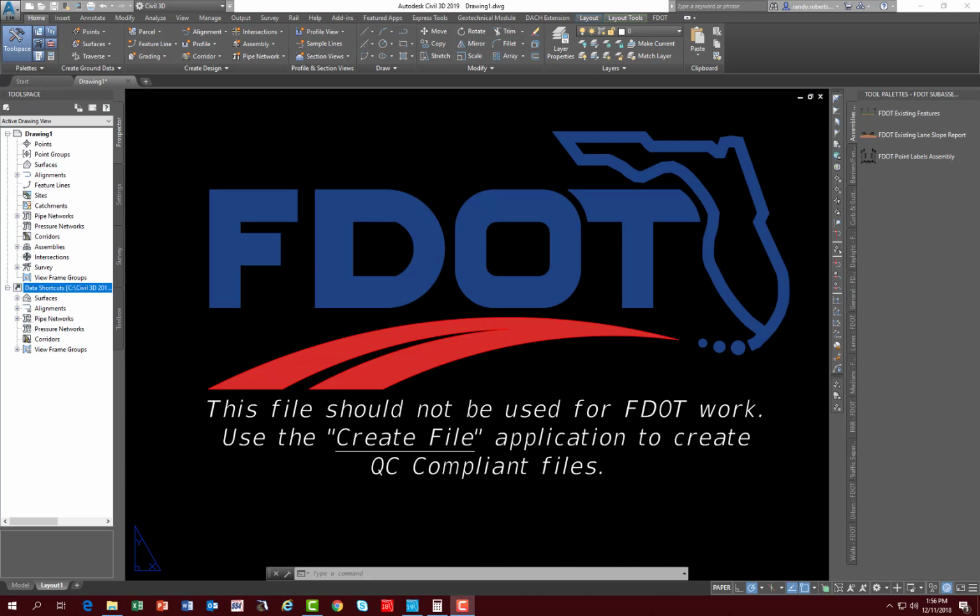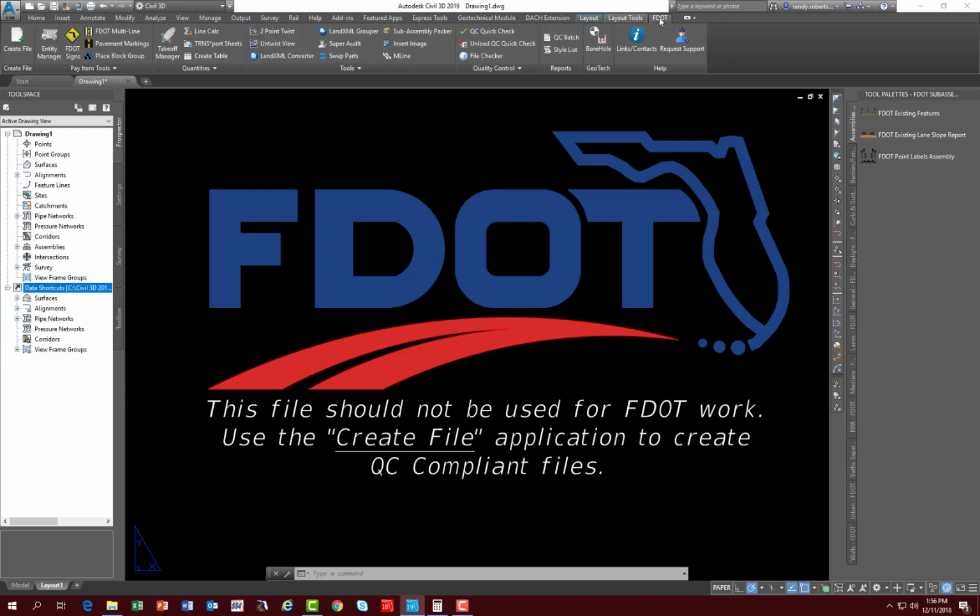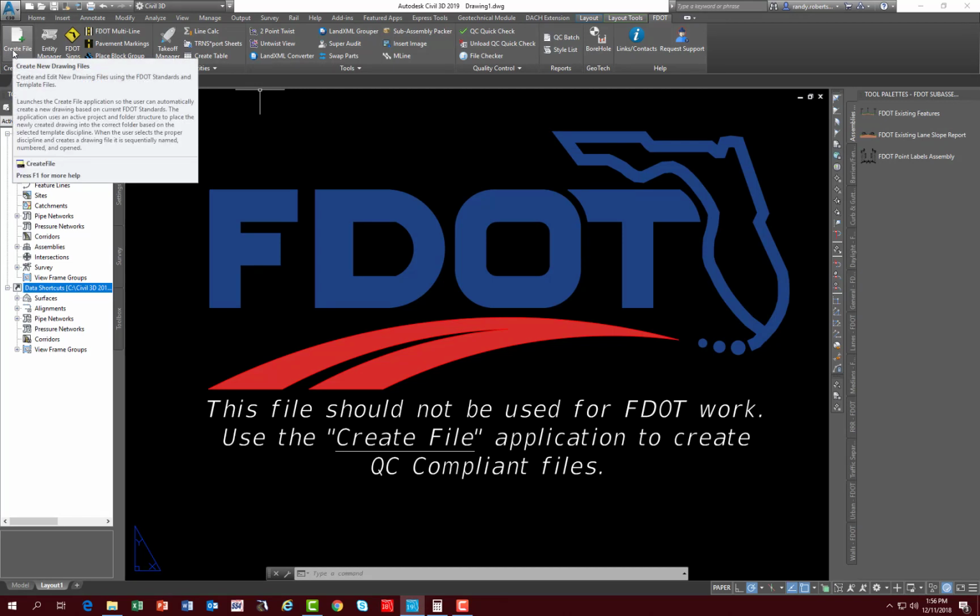The next step that we must complete is the creation of the project base files. With the Civil 3D State Kit open, click on the FDOT ribbon located on the far right along the top. You'll notice an application on the far left called Create File. Create File will create all the design files. The file contains all design file naming conventions along with the appropriate symbology, layers, colors, line types, etc. The application can only be launched from inside Civil 3D.